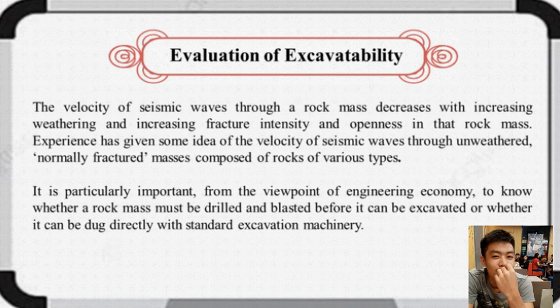Evaluation of excavability. The velocity of seismic waves through a rock mass decreases with increasing weathering and increasing fracture intensity and openness in that rock mass. Experience has given some idea of the velocity of seismic waves through unweathered, normally fractured masses composed of rocks of various types.